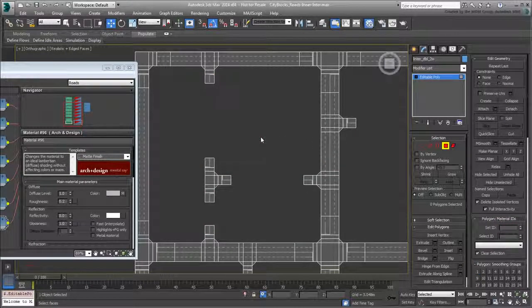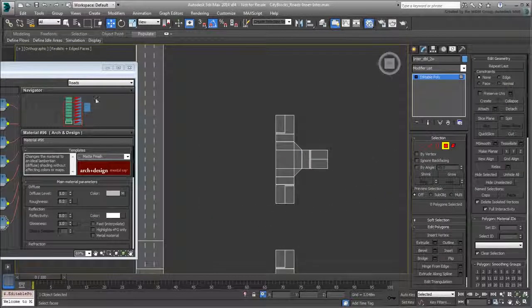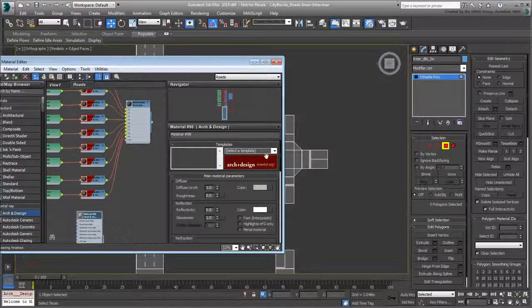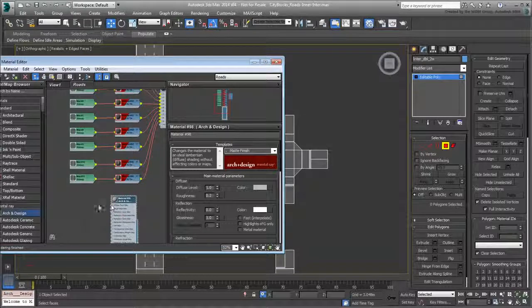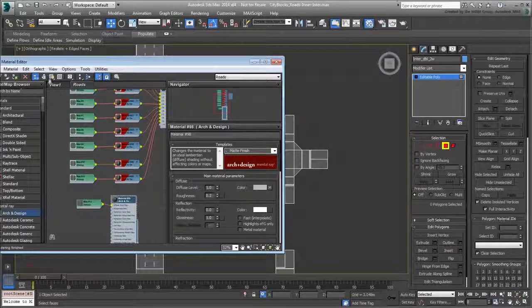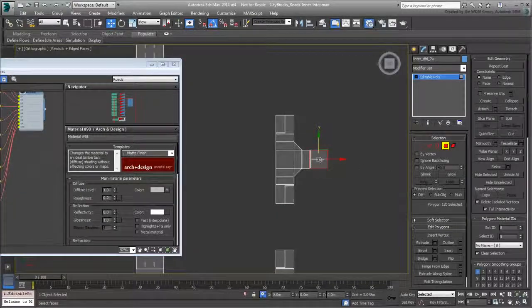When you get to the road that's meant to be one way, setting the ID to 8 works on the right, but not on the left side. The left side should be simply an intermittent divider line, as traffic is flowing left to right. So, add a new submaterial for it, submaterial number 10, based on the appropriate bitmap, and set the face ID accordingly.